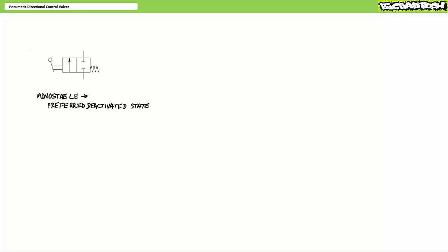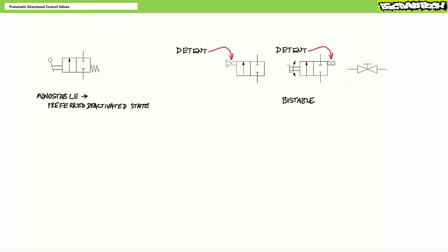This isn't always necessary or desired. You might find certain directional control valves making use of actuators with detents, or pairs of actuators operating in opposition to one another. For example, consider a 2x2 directional control valve lacking an offset spring, employing a manual operator with a detent, illustrated as a triangular cutout. Alternatively, a detented actuator might be illustrated as a regular actuator on one side with a detent on the other.